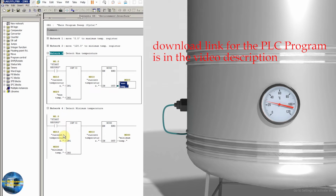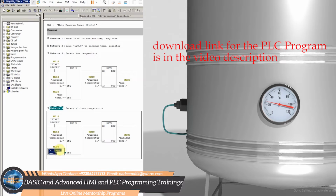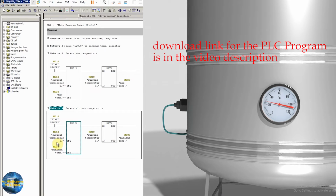As we know, we have started the process, and at that time we shifted 120 degrees into this MD30 data register, and when we started recording, our temperature was 15 degrees. So as we know that 15 degrees is less than 120 degrees, this comparison instruction becomes true.